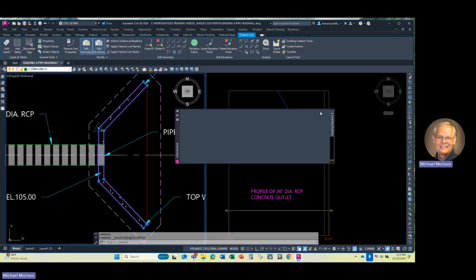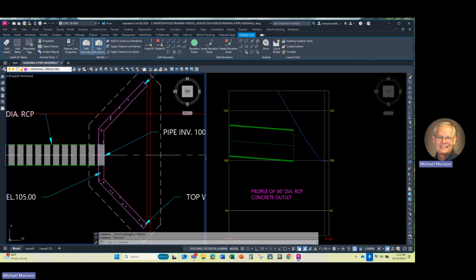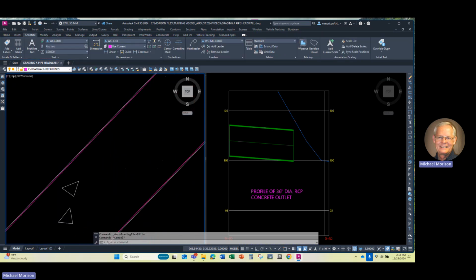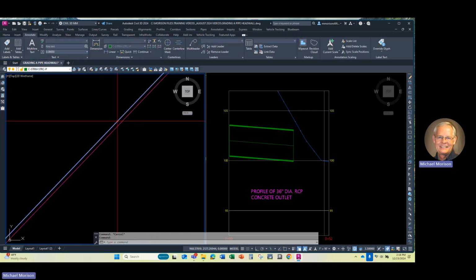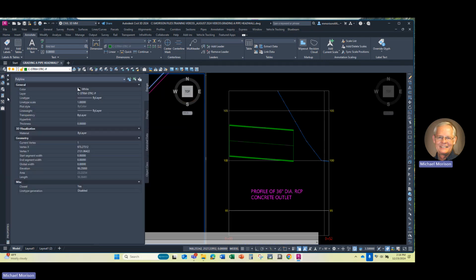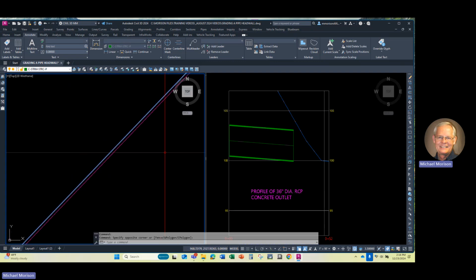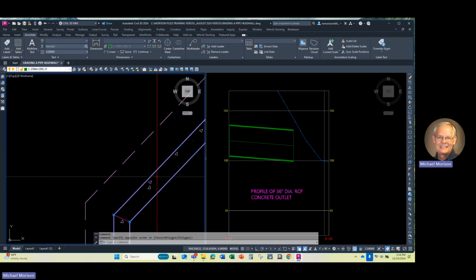And then I have one more feature line or polyline that represents the base of that wall, right? And so this elevation I've assigned to this polyline at a 99.25, which puts it, I believe, like 8 inches below the invert of the pipe. So I want to be able to have a layer of riprap in here. So that's where the top of the footing would be.